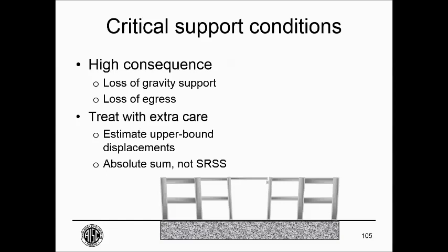So this would be a bridge across a seismic joint, where if there was too much relative movement, you'd lose support. You wouldn't just lose a little joint cover, you'd lose the entire bridge. You'd lose a beam or something significant like that. So where I showed a double column connection in the previous slide, this is a single column connection with a bracket.